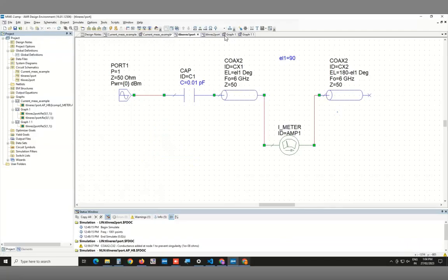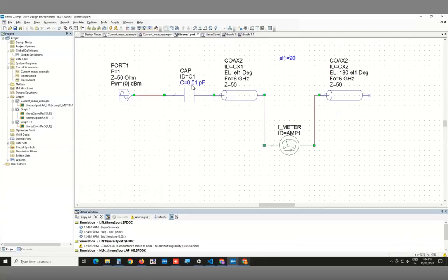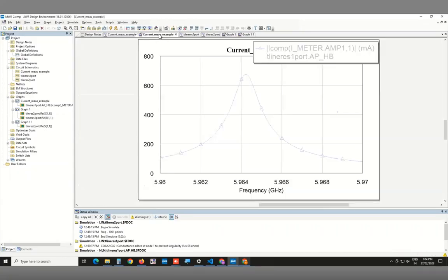See, the circuit is symmetric, right? In fact, if you think about it, this circuit is somewhat less symmetric, in the sense that the open end on this side is a true open, whereas the open end on this side is a small capacitance. So this circuit is actually not truly symmetric. Let's see if we can catch this, whether the current antinode is exactly in the middle or not. We didn't pay attention to this very carefully, but let's see if we can do that now.